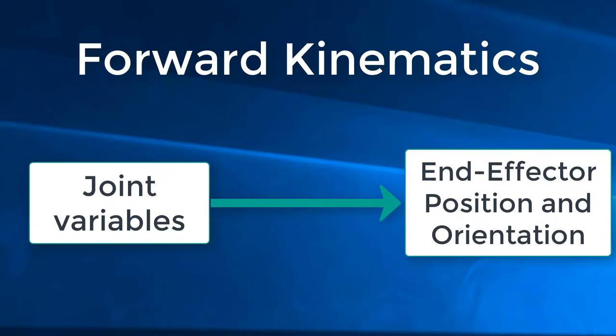For example, in our build, the z equals 0 position is the board. If we would ever calculate that the location of the end effector was at z less than or equal to 0, we would know to avoid that particular set of joint variables because that would cause our end effector to collide with the board. But most often, we're actually trying to solve this problem in reverse.